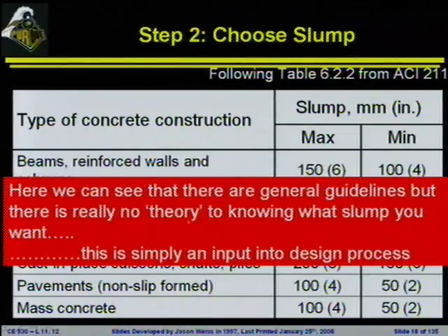If I were redesigning the way concrete mixtures are done today, I would not have slump this early on in the whole process. This table comes from the early 1900s, where there were not chemical admixtures that we could be using to alter the process very quickly. There was not the amount of control we have now, so slump was one of the early things people used, because they were typically placing the concrete by hand.